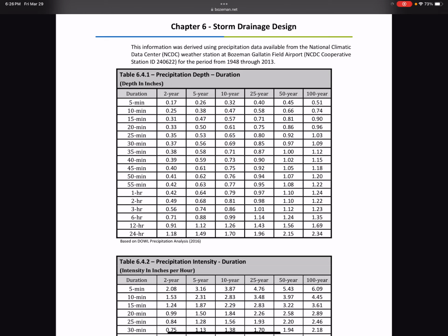So in the rain design chapter in ASCE 7, they talk about the design requirement for the primary and the secondary drain. So primary is like, I don't know, a 60-year or 50-year return interval, I think like that, 60 minutes in 100 years or something. I can't remember, but that one's not the problem. The problem is the secondary. So if the primary is clogged, now all of a sudden we got to look at the secondary. Well, the secondary is going to have to carry a 15-minute duration storm that's coming once every 100 years. Well, you can see from this table here, at 15-minute duration at 100 years, you're at 0.9 inch depth, right?